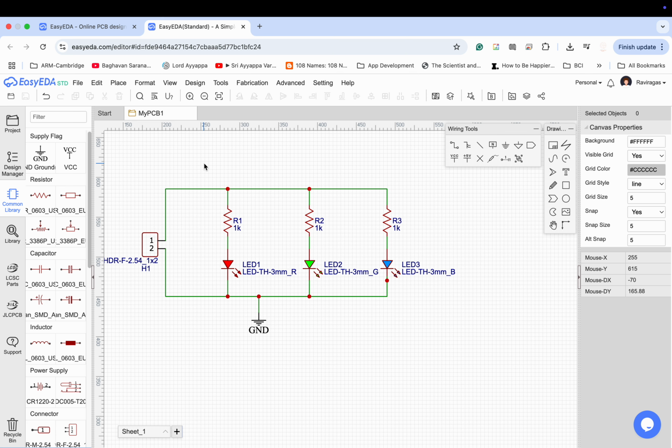When you design a schematic, we base it on the understanding of the symbols and the components they represent. But when you map it to a PCB, we must also take into account the actual footprint of the component, that means the space and the size of the component on the board.